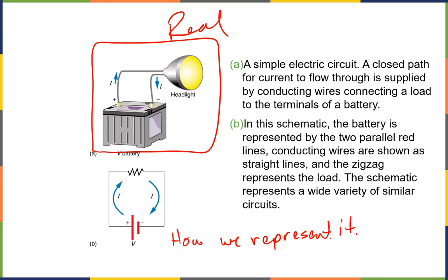So the first thing is, how do you write a battery? And you will see, even with this picture, the picture is wrong. A single voltaic cell is like this. That's a cell. The long side is always the positive, the short side is the negative. And these cells run by chemical reactions that generally produce somewhere in the ballpark of 1 to 1.5 volts.